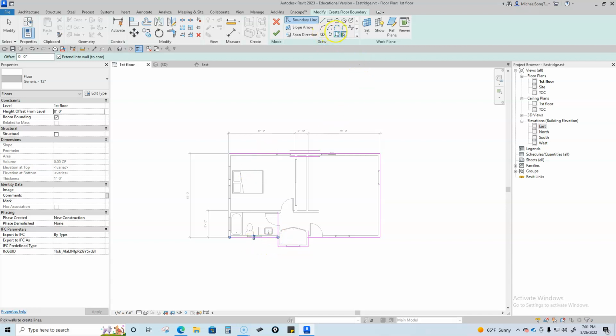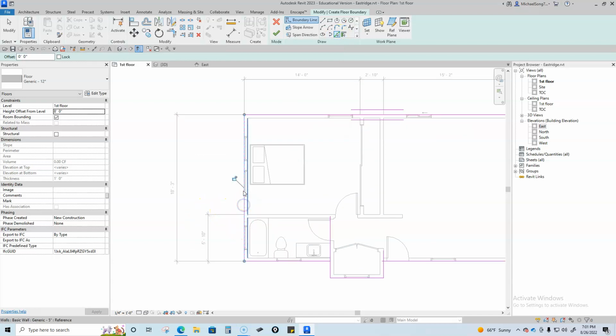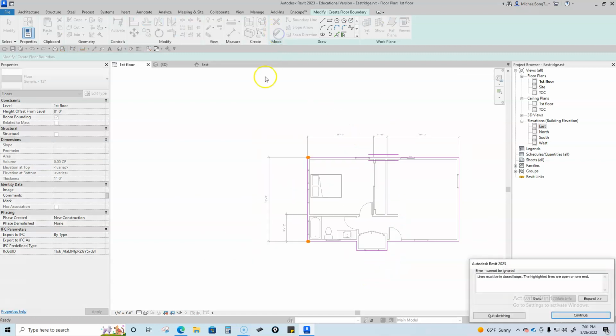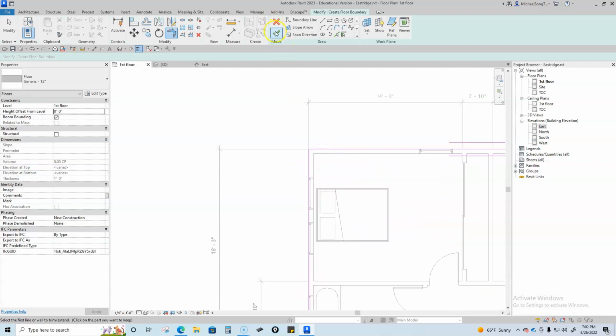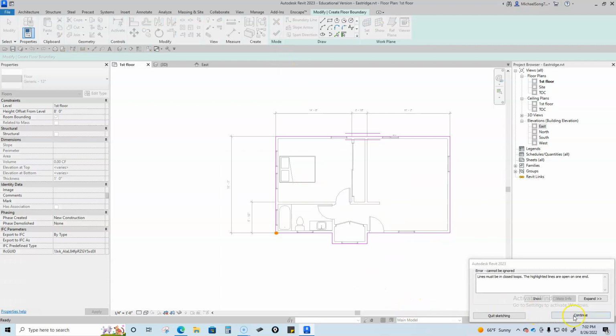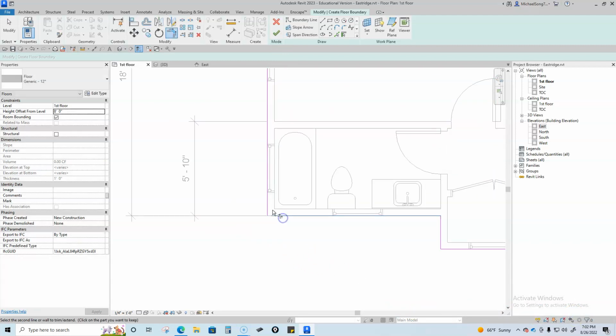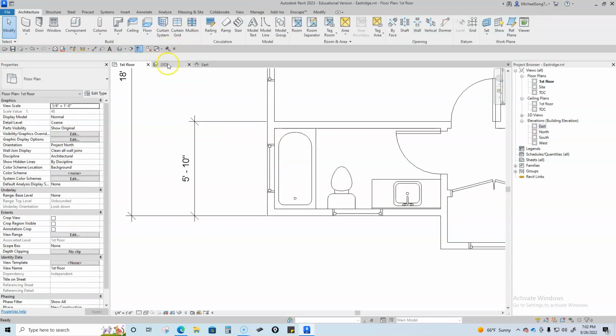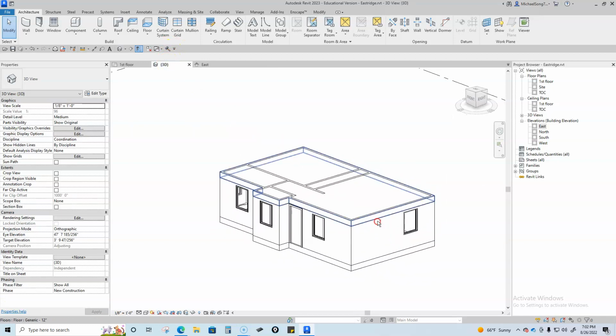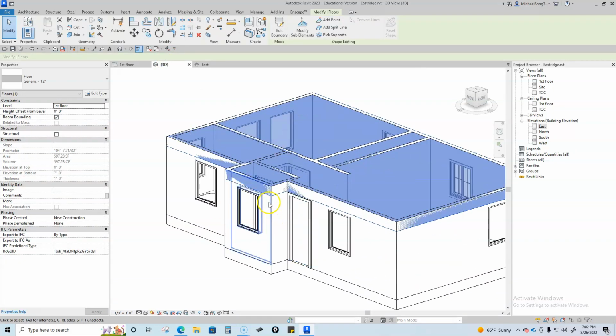You could also use this tool. It's called the pick line tool, meaning you can just pick a line and it'll recognize that as something that it's going to use as a tracer. And then trim, and I'm good to go there. Trim. Okay. So now if I look at that, I have a floor and it's kind of sandwiched in there.